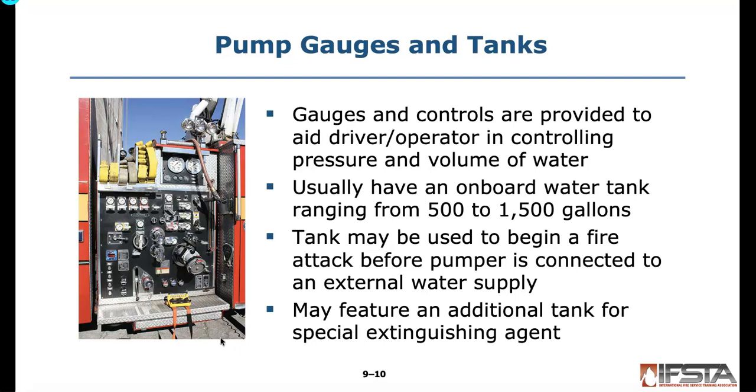This is called the pump panel. This picture that you see, it's commonly referred to as the pump panel, and this is just a series of gauges and controls where essentially what you're doing is you're pulling levers to get water out of the attack line, or also you'll have levers that you pull and they're just opening gates, right? So they're opening valves so that you can have an intake and you can have a discharge, right? That's essentially what you have on your apparatus.